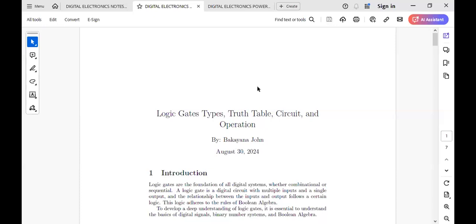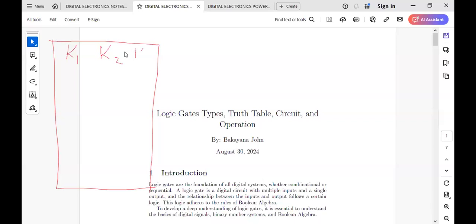The method I had is almost the one that Apia just explained, whereby you first write the zeros in the K1, you write 4 zeros, followed by 1. Then in the second one, you write 2 zeros, 2 ones, till the table gets full to 8 digits. Then in the last one, you write 0 1 0 1 0 1. Then the table will be complete with the right values. Okay, bless you, those are enough.